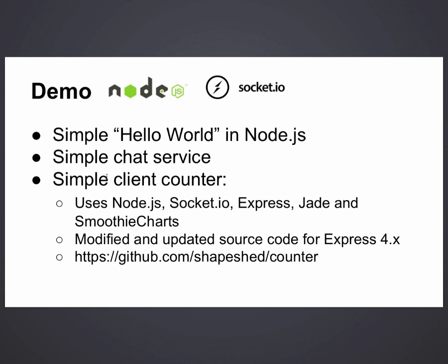Everything is an event, every action is asynchronous, everything is a request to do something, and then separately an event will be generated whenever the task you issued comes back. But the nice thing is that it fits very well with the asynchronous event model, which is very common in embedded devices.